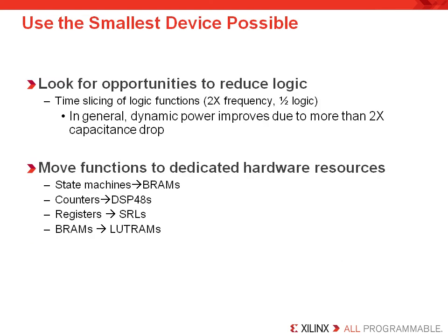These design practices are some of the most useful for reducing the size of your design. Time slicing allows a circuit to perform less work and use less power. Anytime you can time slice your application, the more power you'll end up saving in the application. You should also consider using alternative design practices to target unique and common components to extra dedicated hardware resources. In this example, one of the most useful is migrating a required finite state machine to a block RAM.